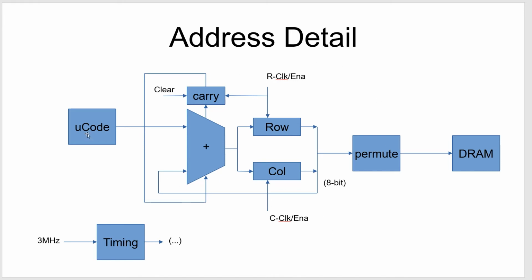So what we do is in the microcode, we have a 14-bit offset that's split into rows and columns. This is, again, nomenclature for the DRAM rows and columns, RAS and CAS signals. And there's an adder in here so that the microcode puts an offset in, and this offset is added every time. So if you put a 15 in here, it's going to count every 15 addresses. Boom, boom, boom, boom. And so it's going to go through the memory in this step, because remember, it takes the output here and adds it back, and this is fixed.